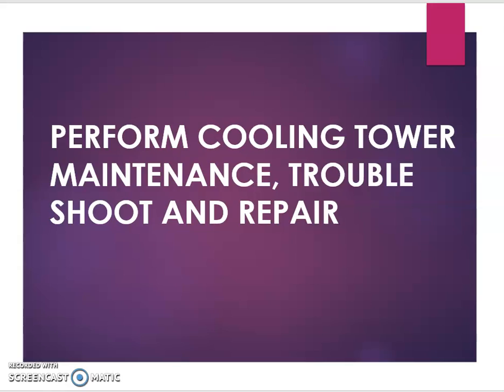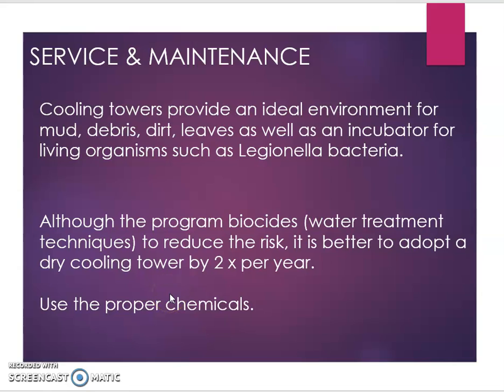So next one, we are going to the cooling tower maintenance and troubleshooting and repair of the cooling tower. So maybe we will highlight the maintenance side first. In a cooling tower, actually, it is a very good place for mud, debris, dirt, leaves, and any living organism to live, because of the wet condition of the cooling tower and surrounding part. So usually a bacteria called Legionella can live in the cooling tower. It is very dangerous if this kind of bacteria is exposed to humans. So we have to make sure we use very good water treatment techniques to reduce the risk.